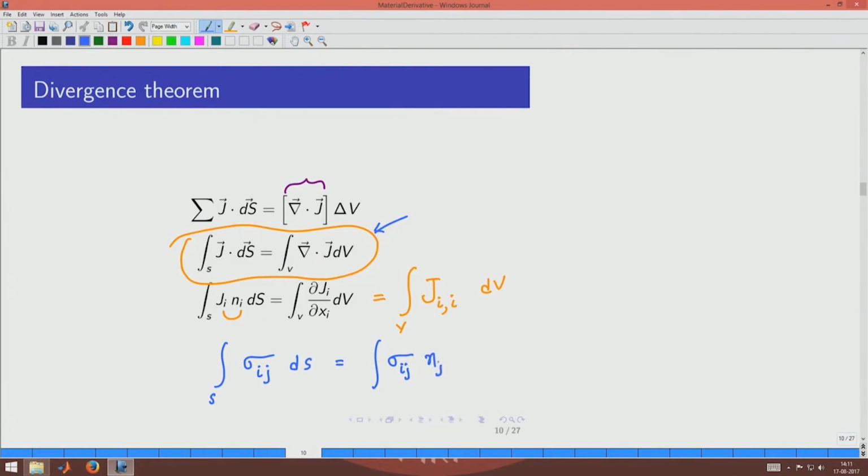So, you choose the index for the surface and dS. Okay. Now, you see that the index that is matching has to go here with the comma. So, you would write this as dou sigma ij by dou x j. Okay. And so, now what we have written is a divergence theorem applicable to tensors of order 2.